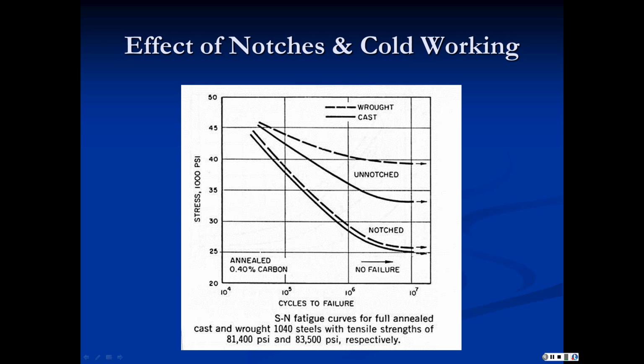If you buy kitchen knives and you like really fancy kitchen knives, if you go look at the company's websites, there's always two grades of knives they sell. One is called a stamped blade, and they simply take sheet which has been rolled to some extent, but not heavily, and they cut out the blade from that sheet material and grind an edge, and it's just a stamped product.